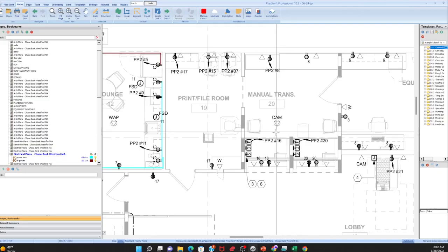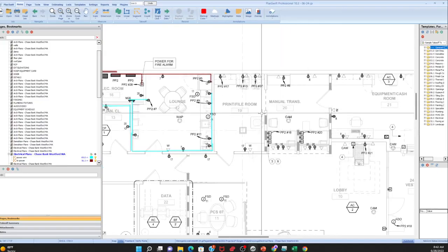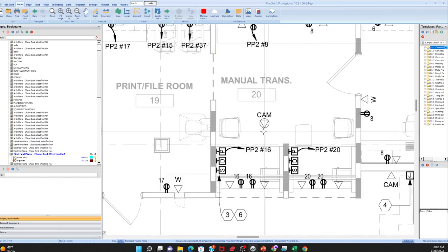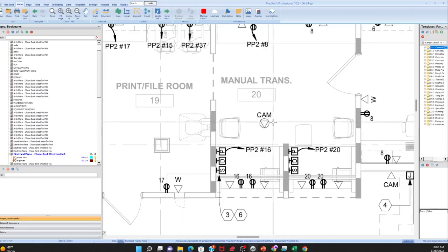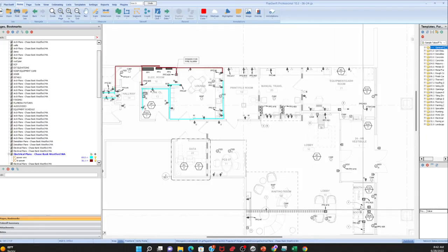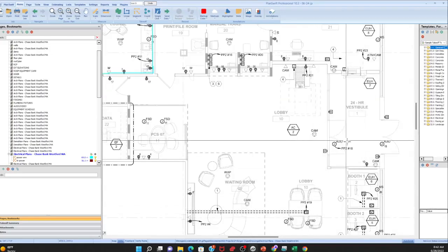So when I go through and I'm finished with my takeoff completely, I'll print it, and then I go through each step and fill in the estimate, like I'm going to show you shortly. All right, so the power plan, that's why we're spending so much time on it, because it's so much little stuff. If you see a symbol in the center of the room, you know it's in the ceiling. And so a junction box for the labor is going to be more to put it in the ceiling than it would be to have it on the wall. So just be mindful of things that are in the ceiling, like that one, and like this.